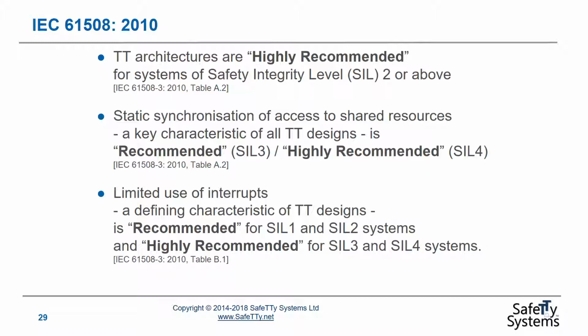Static synchronization of access to shared resources, which is a key characteristic of all TT designs, is recommended at SIL 3 and highly recommended at SIL 4 in IEC 61508. Limited use of interrupts, a defining characteristic of TT designs, is recommended for SIL 1 and SIL 2 systems and highly recommended for SIL 3 and SIL 4 systems in IEC 61508.